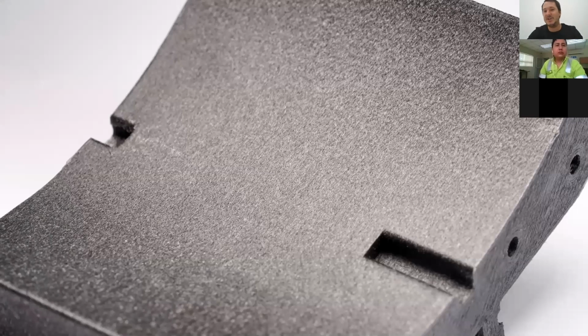So this is actually the main feature that chopped fiber infused plastics can give. So they are not actually bringing too much of the mechanical properties such as strength and stiffness, but by using the chopped fiber, the layers, the visible side surface structure becomes more smooth because of the chopped fibers pointing out.